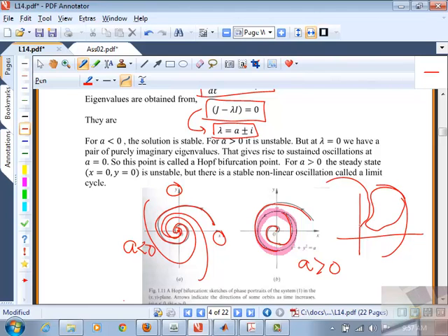This is where the concept of Lyapunov stability becomes more attractive, because we are not saying that it should go to a particular point in state space. If it remains confined in a certain region, you'll still call that a stable state, and it allows that kind of generality. And so you'll call these equilibrium solutions. Okay, they repeat themselves, but dx/dt is not equal to 0 at any point.